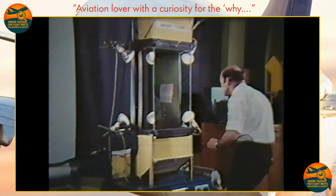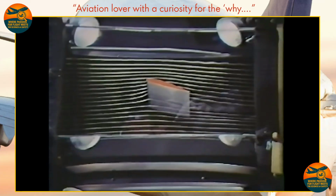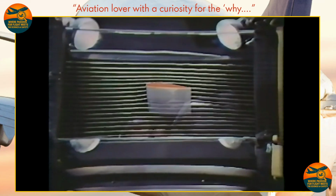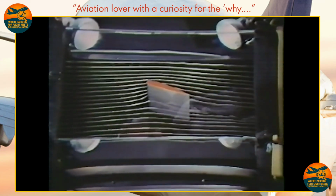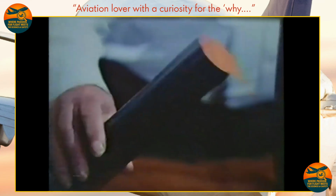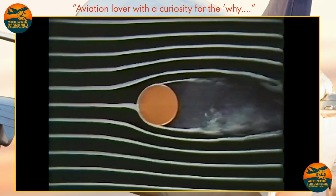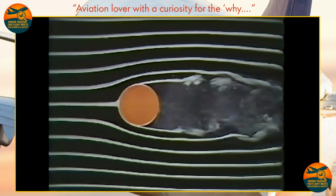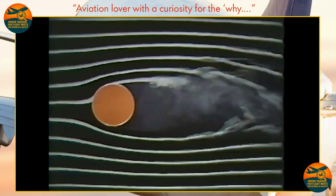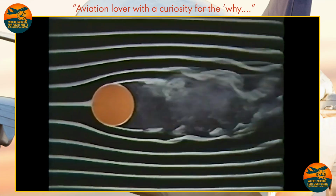We can do this in a smoke tunnel, having first turned it on its side so that we can relate it to horizontal motion. In the tunnel, we can put various solid bodies in the path of the smoke filaments, change their angle to the moving airflow, and see what happens. First, let's take a cylinder. Notice that the airflow curves closely around the frontal curve of its circumference, clinging to it, until suddenly it separates. It can't hold on any longer and becomes unstable and disturbed. It's moving too fast to tuck in behind the cylinder and maintain contact with it, so it has to let go.